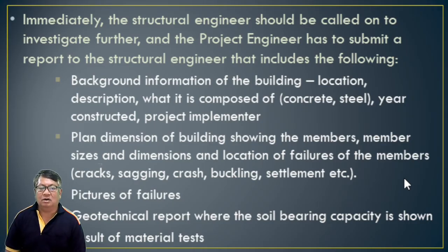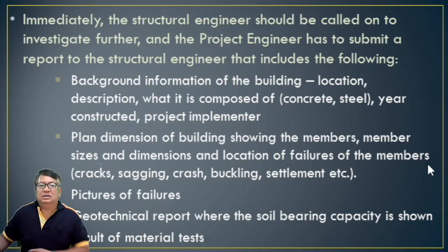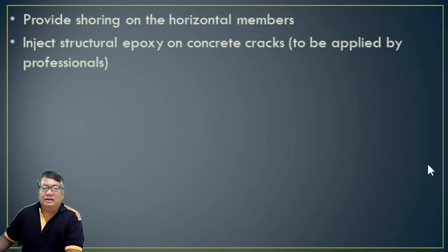Pictures of failures. Every time, you must take pictures for evidence and for comparison of any movement or differences between the present and the previous position or situation. Geotechnical report where the soil bearing capacity is shown. Results of the material testing. So try to show and share these to the structural engineers. So provide shoring in the horizontal members and inject structural epoxy on concrete cracks, to be applied by the professionals.